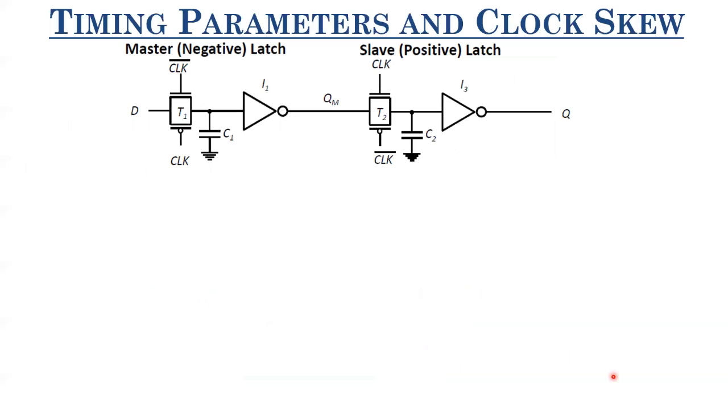Now, as we have done for the transmission-gate-based edge-triggered register, let us try to find out the setup time and hold time even for this kind of dynamic register. I discussed this in the previous discussion session, and that discussion was also correct, but now I have understood why exactly Rabaey or other people do not include this inverter in the setup time, and I'll be discussing that. What they are considering when calculating setup time, hold time and the TCQ, and what we are considering. So let us go ahead and discuss that.